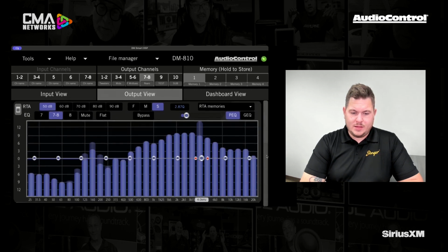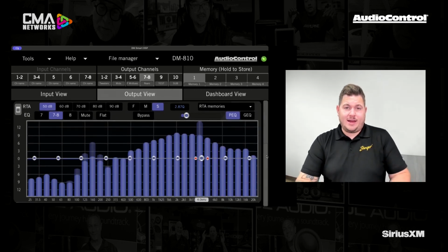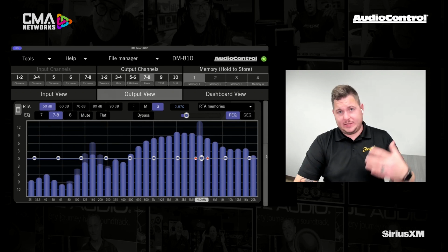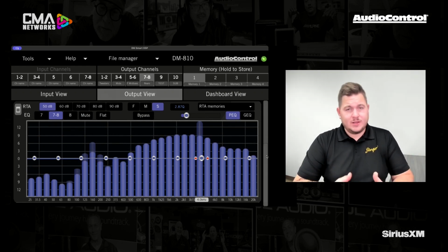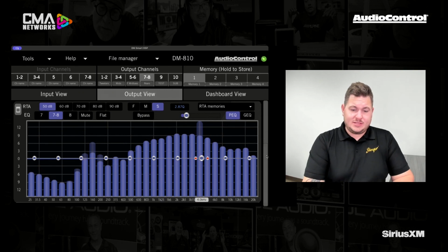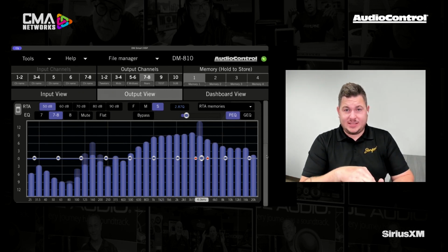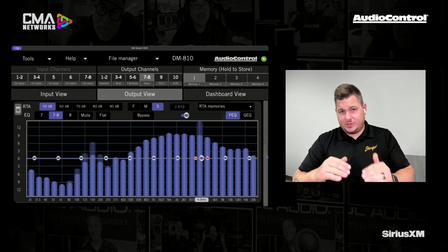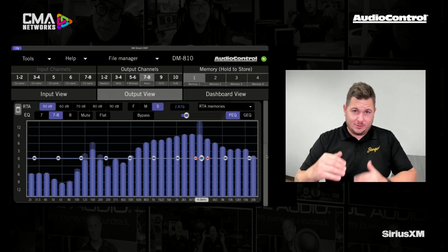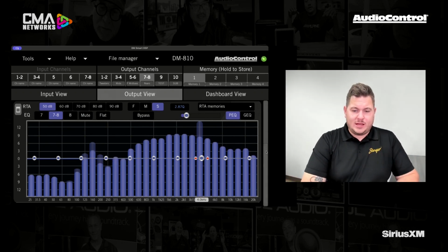There we go. And you can see we do actually have a full range signal. By combining channel 5 and channel 6 together, we were able to achieve full range. The only problem is you can see the mids and highs section is definitely going to be a fair bit louder than the lows, because that signal was weaker and the mids and highs signal was stronger. So how do we combat that?